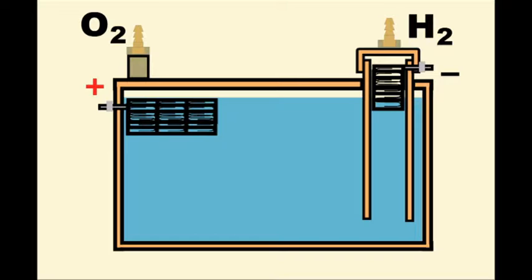The hydrogen production chamber is shaped like a piece of pipe containing a certain amount of water inside it, so the hydrogen cannot exit the pipe and go into the section where oxygen is being produced. If we reduce the amount of hydrogen exiting the cell, or totally close the valve that controls the output, the production chamber begins to accumulate hydrogen and displacing the water contained in the pipe. If this goes on and on, the hydrogen could completely displace the water from the pipe and could mix with the oxygen being produced in the left section of the cell.